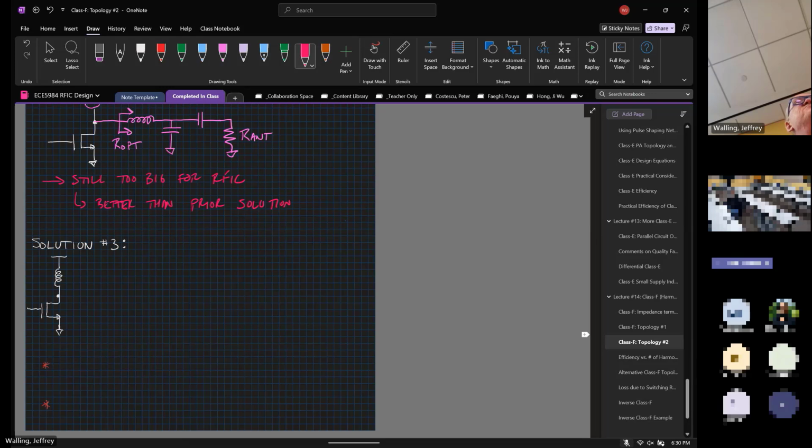Yeah, people do this in research frequently, but for a pure RFIC. Now, we're also talking about CMOS power amplifiers, and there are only a few niche cases where you can use a CMOS power amplifier. You can get away with it in connectivity applications like Wi-Fi and Bluetooth for lower power things, but for anything higher power, it's almost always going to be a III-V MMIC.